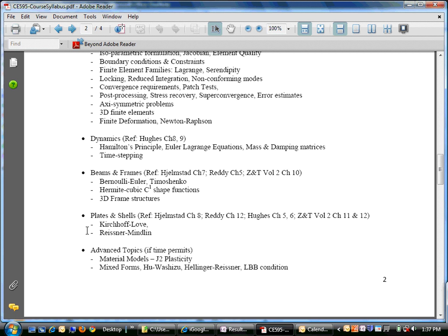The underlying theory of continuum or solid mechanics is divergence of stress plus B is equal to 0. All your strain measures and all that are pretty much set in stone. It's the ingenuity of the structural engineer to think about how something is going to deform, and then figure out what equations this theory leads to.